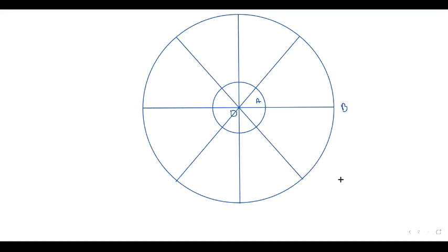First we divide the circle into 8 equal parts. And give the numbering such that if we start from this, this is 1, 2, 3, 4, 5, 6, 7, this is 8. Again half convolution, so this is 9, 10, 11, 12. Because 1.5 convolution is given, so one full rotation, then again half rotation.